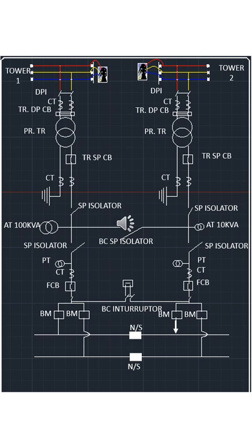This is the capability of an interrupter. You can close it from no load to full load to faulty condition, but if you close it during faulty condition, the circuit breaker will trip and the section will be protected.